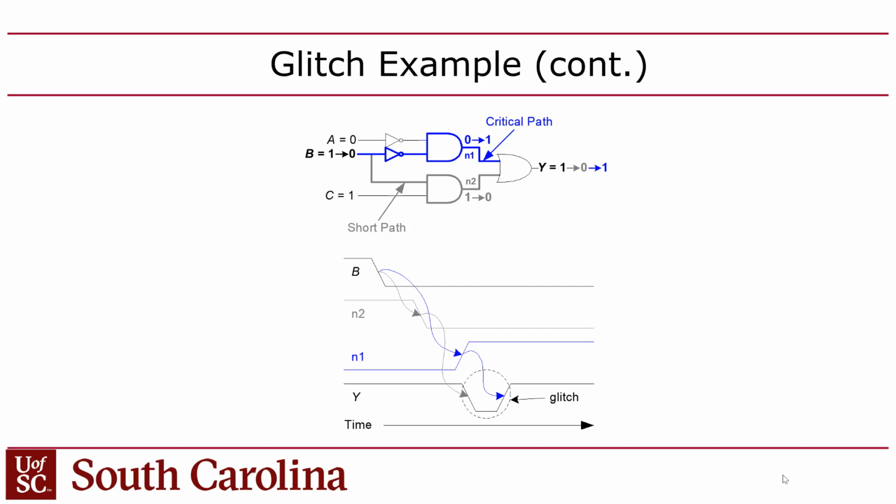And there will be a brief amount of time in there where the OR gate is going to see initially 1, 0, which gives you a 1 output, and then it's going to briefly see a 0, 0, right? Because the bottom input was a 1. That was what was sustaining that OR gate's 1 output. But it's going to drop right away, and the OR gate is going to see a 0, 0 until the top AND gate catches up and then puts a 1, and then you'll end up with a 1, 0 in there, right? So what will end up happening is you'll see this glitch.